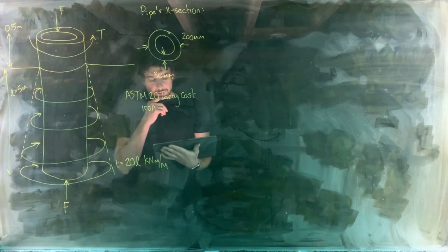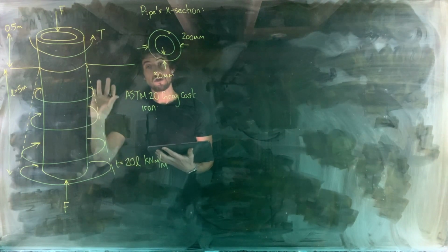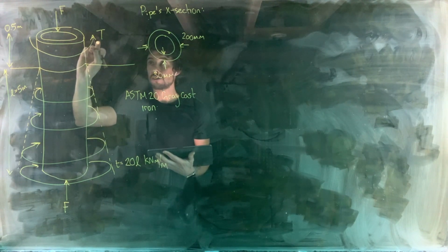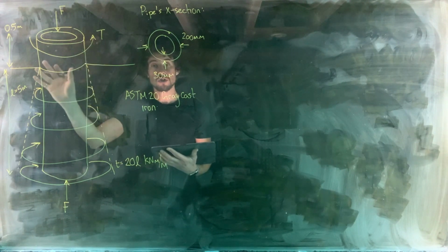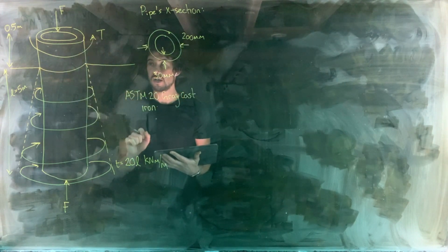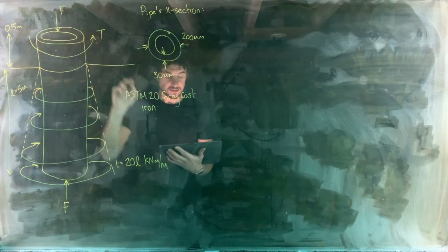In order to rotate the pipe without causing fracture when under applied torque T, so if we did increase T sufficiently to overcome the frictional resistance to rotation of the soil, the pipe would rotate. But of course, applying torque T, which would cause shear stress, by stress transformation would result in a tensile stress too. And gray cast iron being a brittle material, it would be sensitive to tensile stress, but we'll look at the material properties in a second.